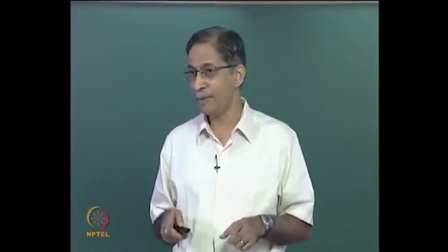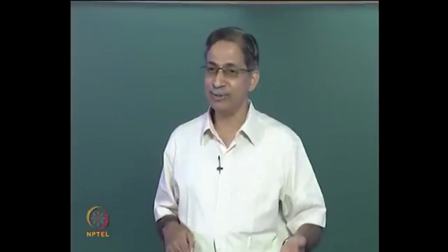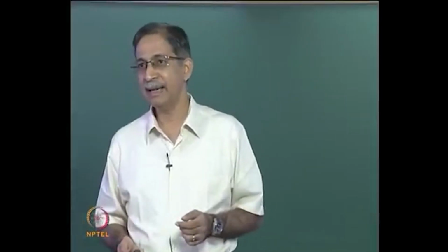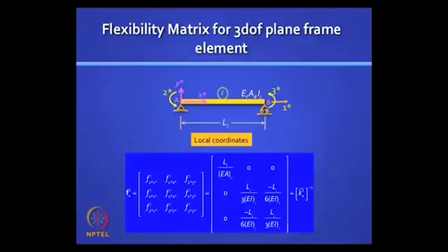That is an assumption we are making here. We will see through that assumption in the next module and we will bring in that interaction. Right now we accept this and you can do it at the other end and generate your flexibility matrix. Very easy to remember because you know what you did for a beam element,